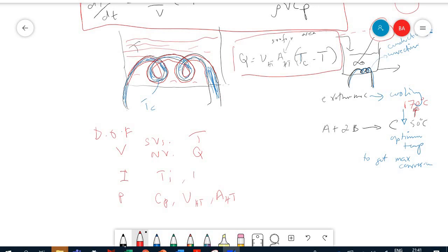And by the way, one of the inputs also is Tc, because we identified the temperature of that cooling water. So that is considered also as an input. If you consider it as a constant or parameter, it's okay. Whether you put Tc here or there, it's not a big deal. The simulation will run similarly. It depends on whether you want to use Tc as a manipulated variable. We don't know what the manipulated variable is yet, but if you use it to control the temperature of the reactor, then in that sense you will put it as an input and not as a parameter.